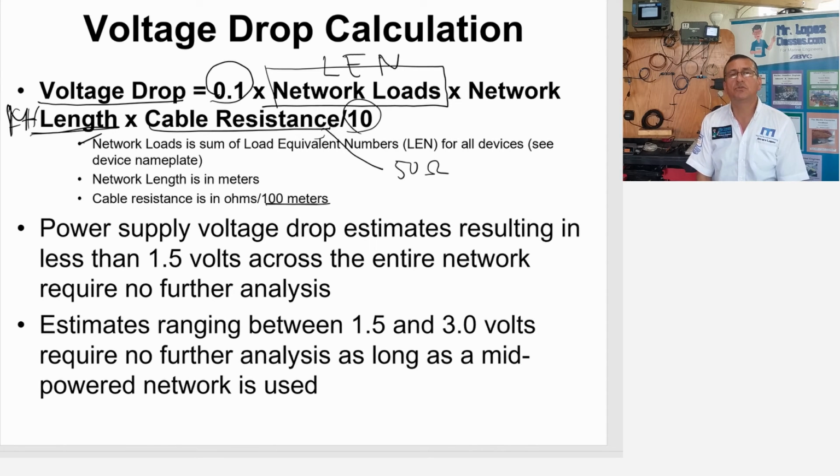And immediately you solve the problem, because calculating, according with my experience, is difficult. Suppose that you have mini cables for the trunk, and mid cables for the drop lines, and you need to calculate the total and the cable resistance. You have different cable resistance, and you don't know exactly what that amount is. For that reason, I prefer, according with my experience, to follow the recommendation of the computer.